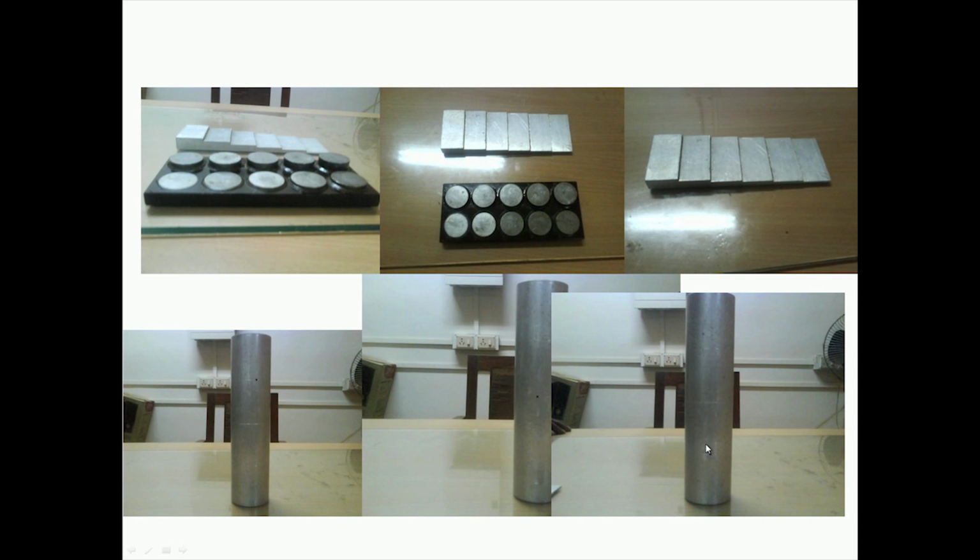So, like this you can make this kind of artificial flaws on these reference standards or standard blocks, and since the location and the depth of these defects are known, you can get an echo from each of these defects and then see on the display screen whether that echo is coming at the place or at the time where it is supposed to come. So, like that by collecting the data at different depths you would be able to calibrate the instrument.